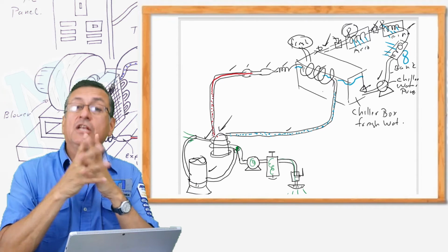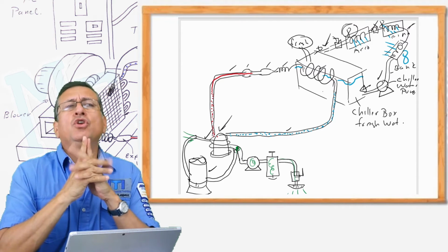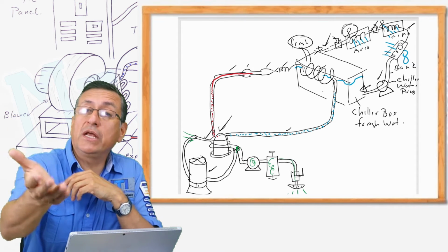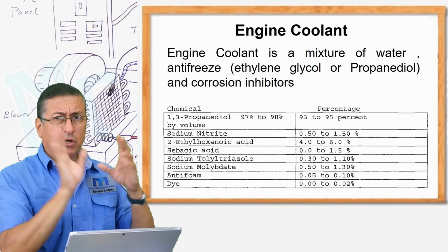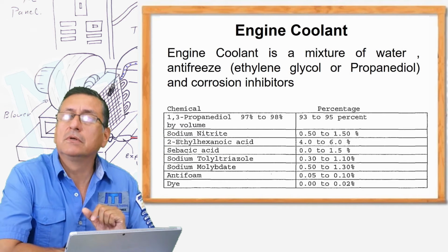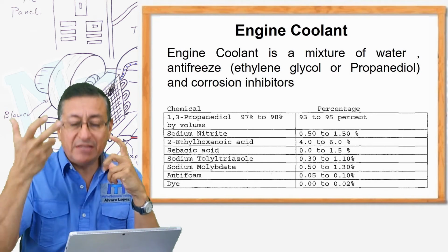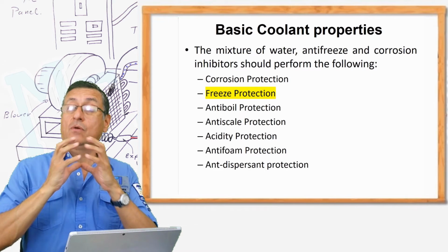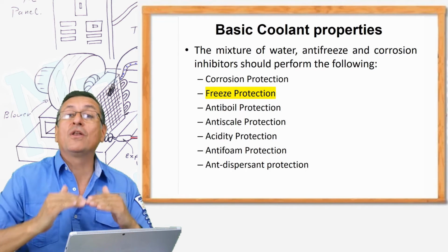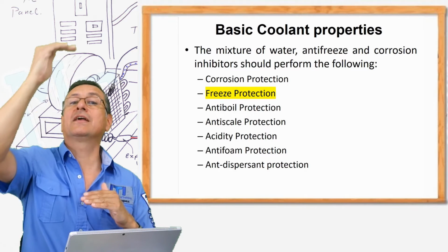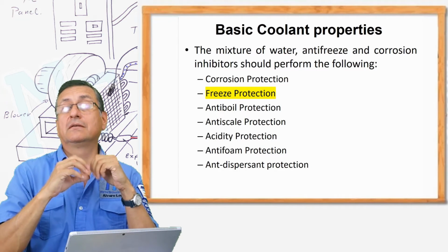All right. Normally, in industrial applications and also in marine applications, they don't use fresh water. They use coolant, similar to the coolant used in the radiator of your car. Do you remember the composition of that coolant? You remember from our diesel and gas course, it is glycol. It's 50-50: 50% glycol and 50% water. And do you remember the advantage of that system? Yes, one of the advantages is that the freezing point will be lower, and the boiling point a little higher. This is good because you avoid the water becoming ice easily.